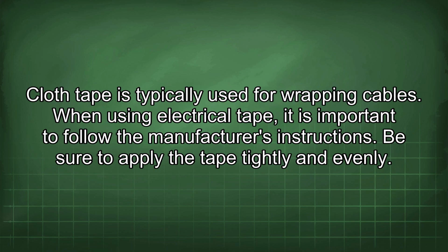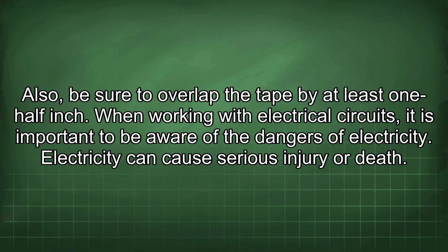When using electrical tape, it is important to follow the manufacturer's instructions. Be sure to apply the tape tightly and evenly. Also, be sure to overlap the tape by at least 1/2 inch.